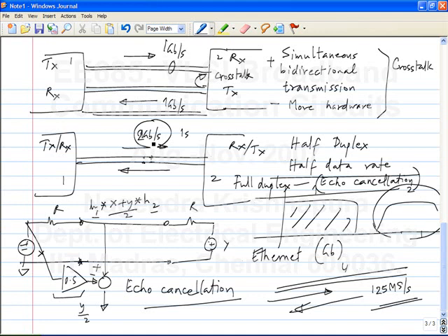In case of crosstalk, depending on whether you know the data or not, you may or may not be able to cancel it. For instance, again in Ethernet there are 4 pairs of wires, they are all twisted together. So what you transmit on wires 2, 3 and 4 will interfere with what is being received on 1. In fact, what is transmitted on 1, 2, 3, 4 will all interfere with every wire. So for each one you have to have cancellation schemes. But then you have all 4 channels being received on the same chip, so you know what is being transmitted, and you try to cancel it out. But you can't just multiply it by a number and cancel it. It has to be some complicated filter, and the filter has to be adaptive.